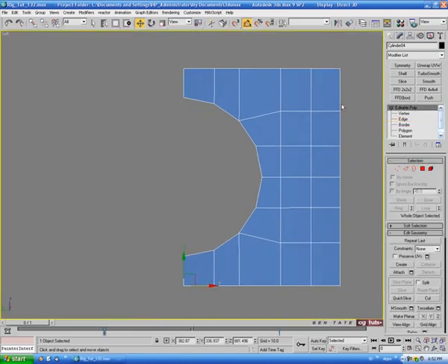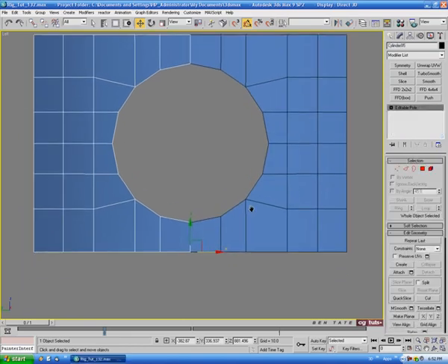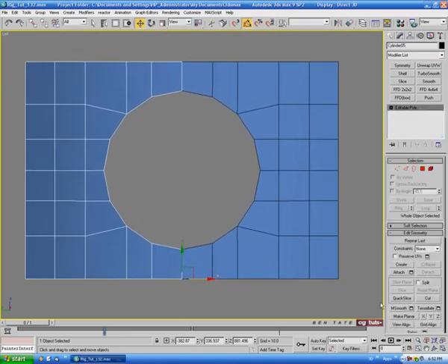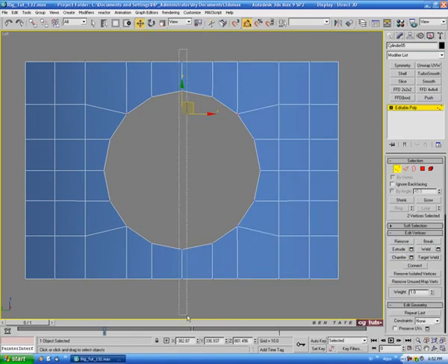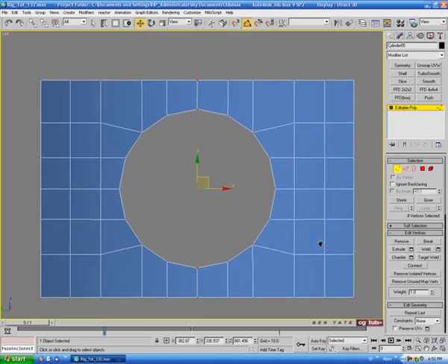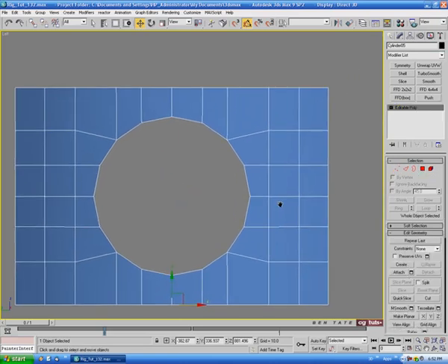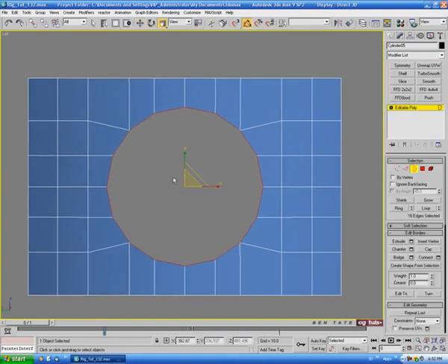And back in the left view here, I'm just going to mirror this over as a copy on the X. Right, let's attach together for now, and we'll just weld up the center verts here. So do weld nose. Okay, and let's also grab the inner border here, and we'll just shift drag this in to create a support edge. And we're going to do that pretty tight.